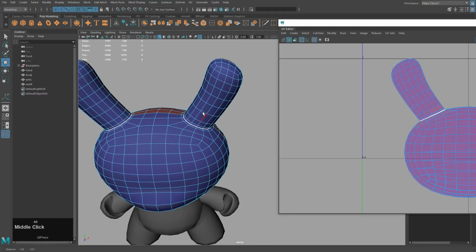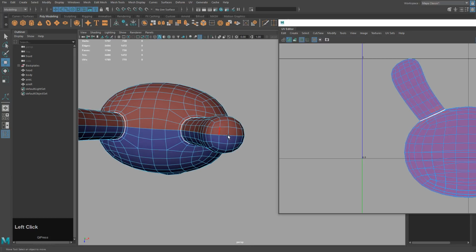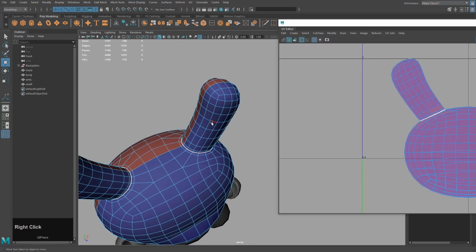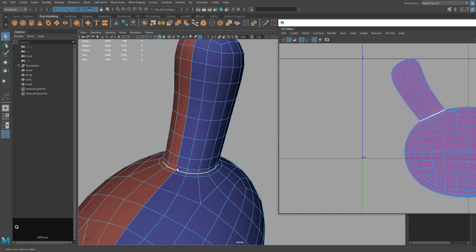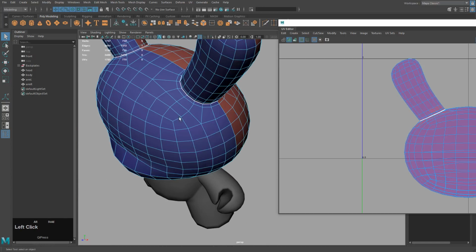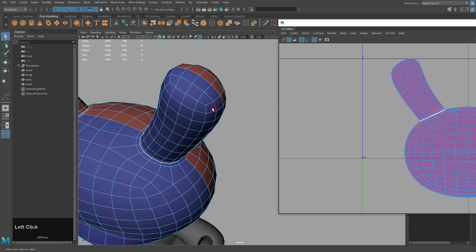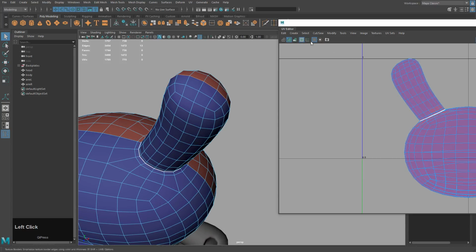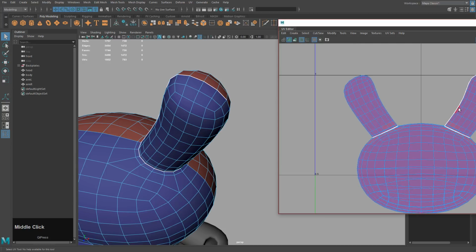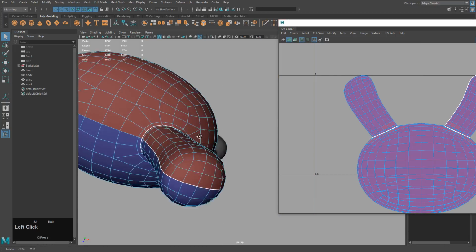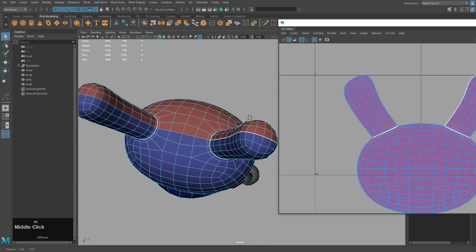This is the border edge line, and it's telling us that this has been cut. Now what we need to do is separate the ears, and the best way to unwrap it is to cut along a seam. So I'm going to left click this edge, then hold shift, go to this end of the ear and double click this edge. If I now click cut and sew, cut, you can see I have an edge cut here now. What we're trying to do is unwrap it, keeping one edge still here, and unwrap it kind of like a sock.